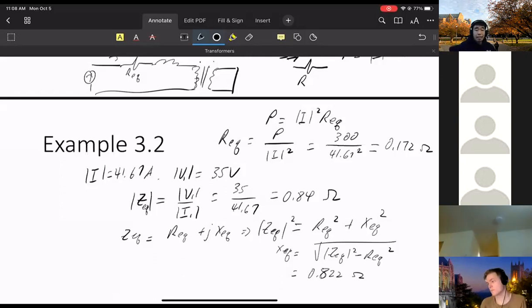And to do this, if we have a 60 hertz signal, then to get a reasonable measurement, you have to measure at least a couple times per cycle to have anything reasonable of a phase measurement. So that means you basically have to measure at hundreds of hertz or kilohertz. That is expensive. You need an oscilloscope, and you have to tune the oscilloscope.